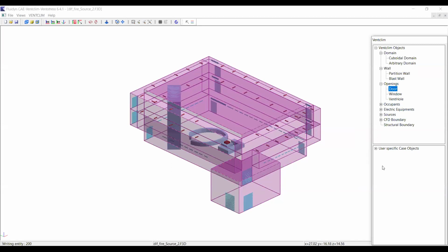If you define a door or window, the GUI will show only the open condition as an option. If you define a vent hole in the GUI, it shows open conditions, but we have provisions for two: if you want to close it, we can close it, otherwise we can open it. That's the main difference in the openings.